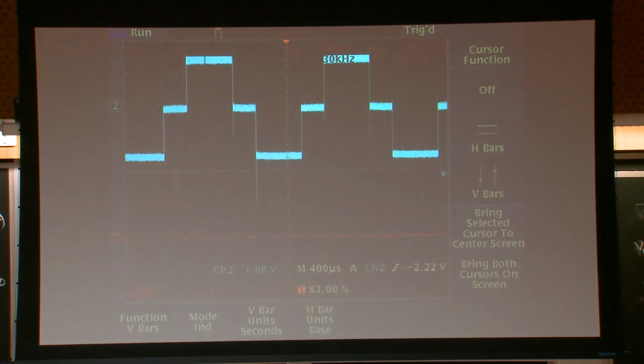As we saw in class, it uses the 3 levels, 0, positive, negative, to create something that resembles a sinusoid. It has half-wave symmetry, so we do not have any a_2k, b_2k, or the even harmonics. We only have to worry about the odd harmonics.